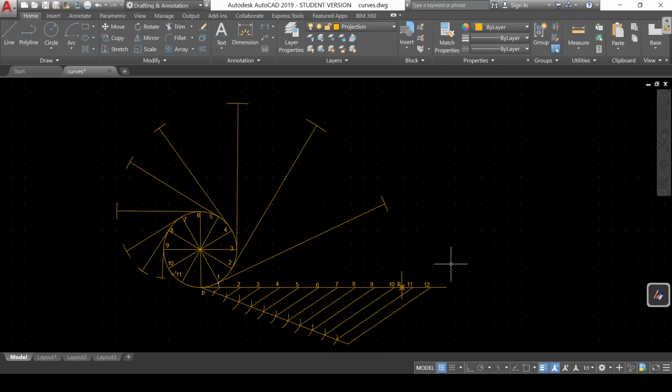See, this is what we have drawn now. This is the circle of 56 mm diameter. So 28 mm is the radius. We have divided this circle into 12 equal parts, and we have drawn a line equal to the circumference. It is around 176 mm here. Divided that line into 12 equal parts by the standard procedure. You see that we have to mark point P, which is at 156 mm from this on this line. So from this point we have measured this 156 mm and cut there. From the starting point we have taken the point P at 156 mm.